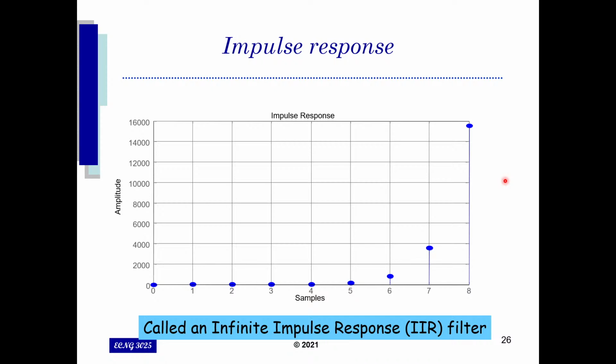Typically, if you're using MATLAB or some other evaluation software, there will be a command that you can just plug the Z transform equation into and it will give you the impulse response automatically.